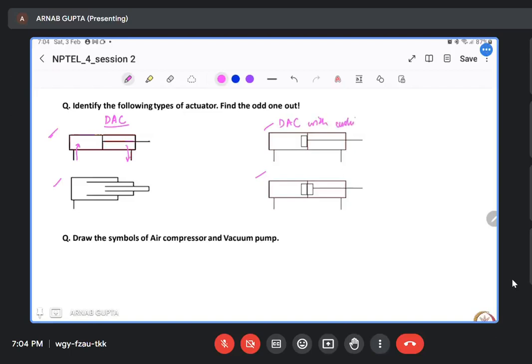with cushion. So again, liquid can flow in through here and flow out through here. While the piston is returning back, it won't touch the end of the cylinder. Rather, it will be cushioned by this particular thing, and this is present only on one end of the piston. In this case, again a double acting cylinder, but the cushion is provided on both sides. So at both the extreme ends, either here or here, that cushioning will be effective.